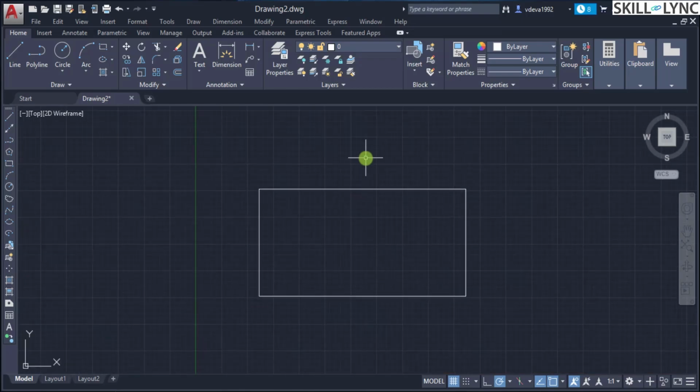So if I click on 500 mm, the height or the width of the window is being specified as 500 and the zoom is done accordingly. Based on the requirement, you can specify the object in hand, and with the height of zoom, you can zoom in or zoom out based on the application. So this is the zoom to center option.